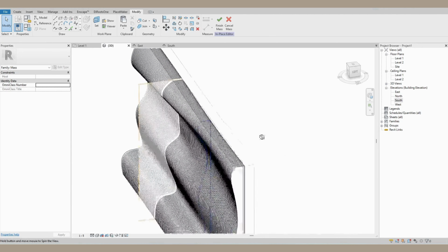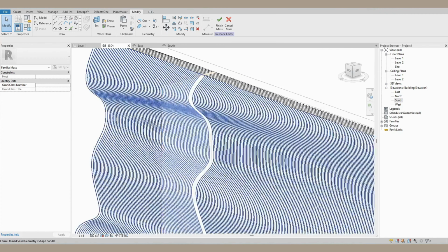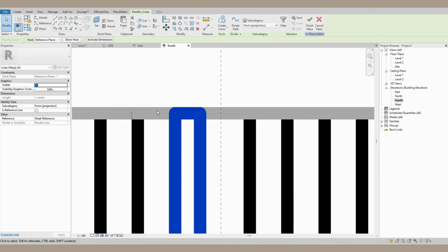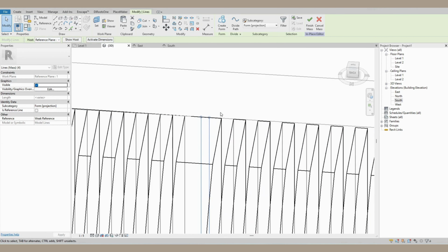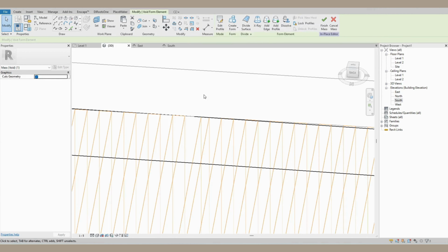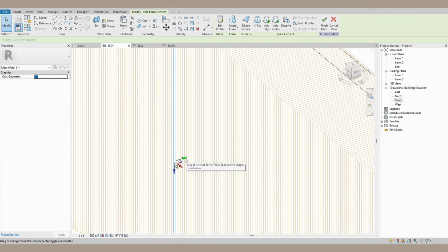Great, then just go into 3D and click on the model line. And just remember to create the form. Make sure to create a void form. Click on the top in the taskbar. Great, just make sure you get it somewhere in the middle, because remember, we're cutting 30 and having a slat by 30 as well. Create form, and let's hope we get a better pop-up this time. Great, and it's been cut.